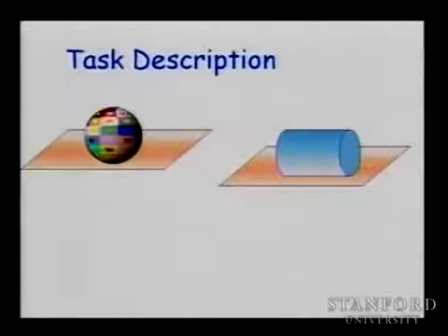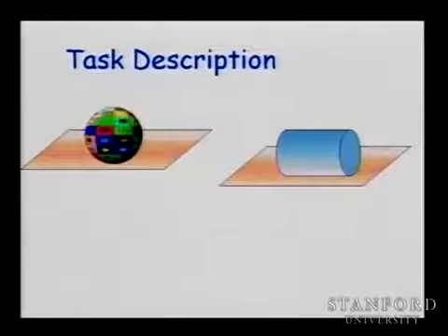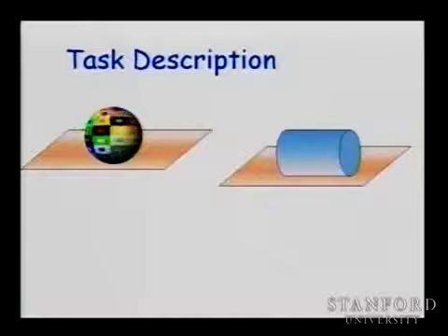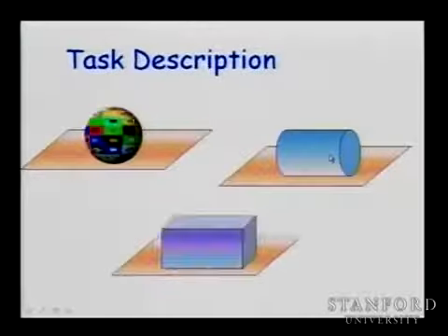5. You lost, yes, 2 in position, and then you still do rotations. You still have those rotations. So you lost 1 degree of freedom by this constraint, contact constraint. How many degrees of freedom we lose here? More than 1? 2. We lost the z-axis, and we lost the rotation about the y-axis, this axis. You cannot rotate about this axis. Okay, how many we lost here?